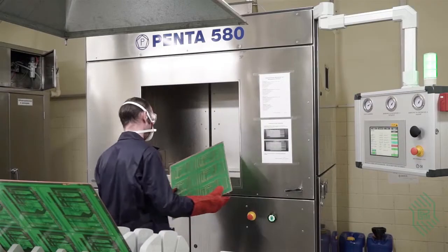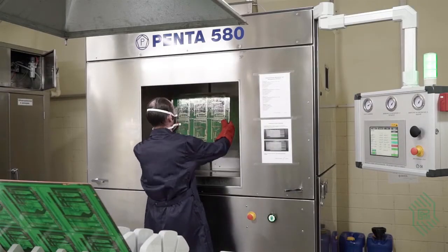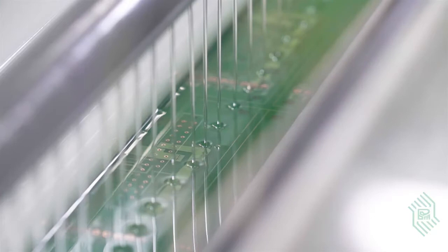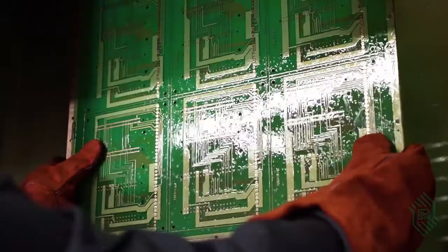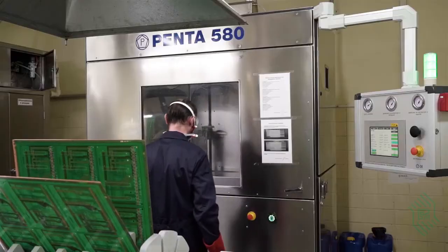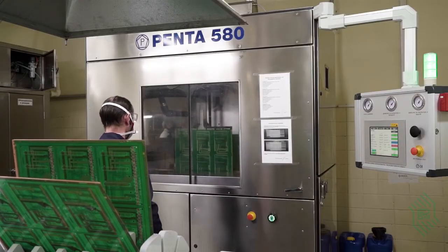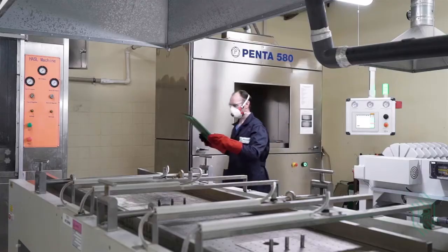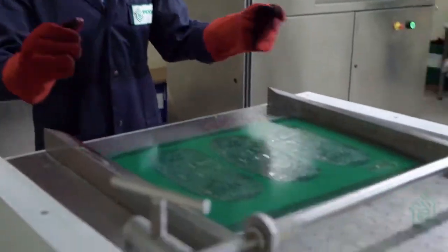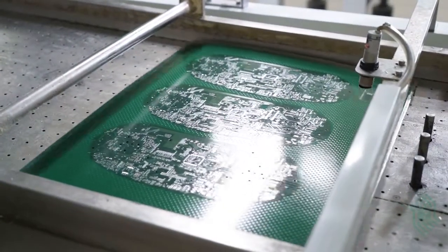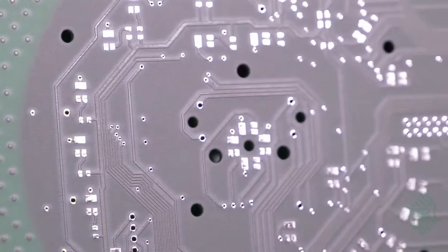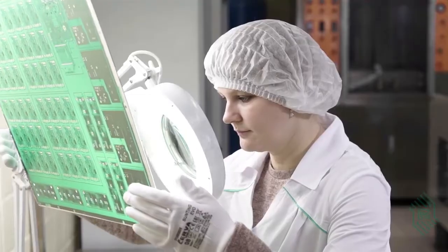For coating the pads with tin lead solder, a hot air solder leveling method is applied. The panels pass through the preparation line where they are cleaned, and then the flux is applied. The prepared panel is plunged into a bath of molten solder for a few seconds. The solder covers all the open copper sections of the panel. During extraction, the excess solder is then blown off with hot air, and a thin, even coating remains on the pads. After cooling, the flux residue is washed away on the cleaning line. The panels coated with solder pass through midpoint quality control.